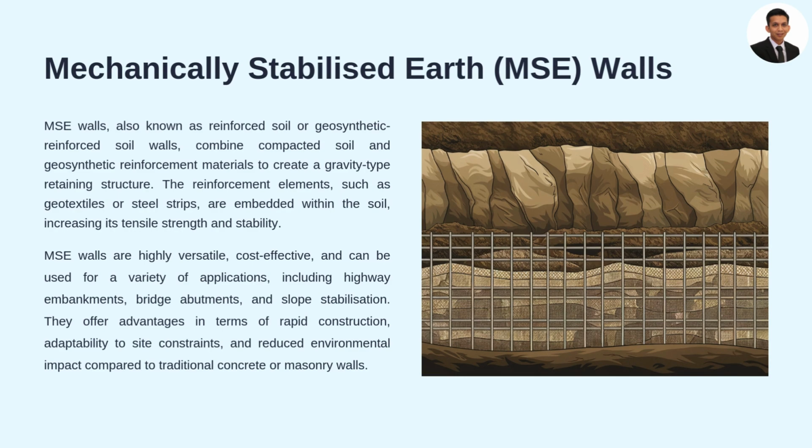Mechanically stabilized earth walls, MSE. MSE walls are an advanced retaining solution combining compacted soil and geosynthetics. Advantages: cost-effective and quicker to build than traditional concrete walls. Environmentally friendly as they use minimal concrete.